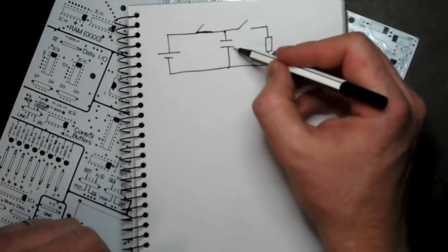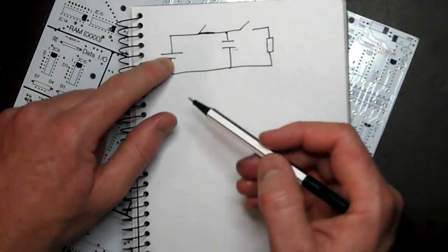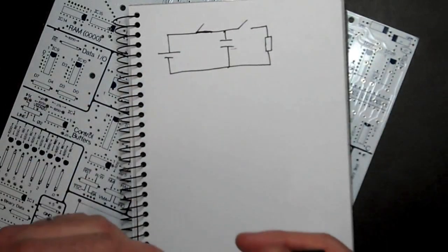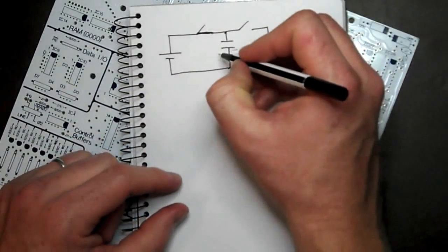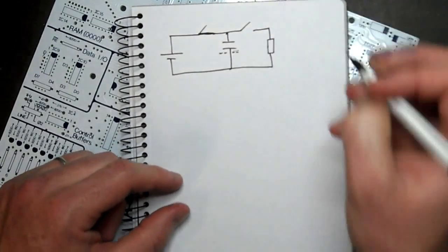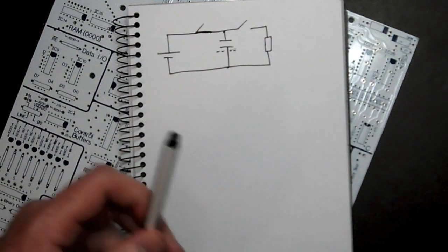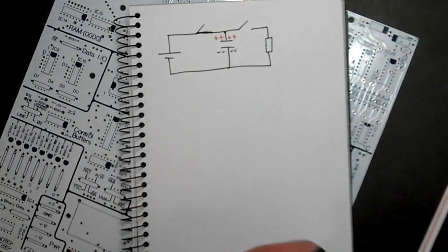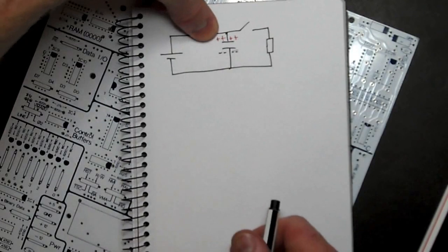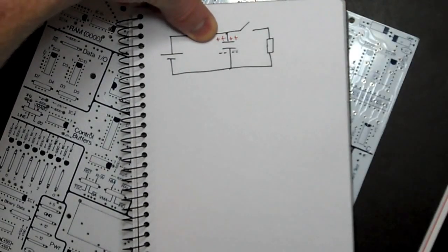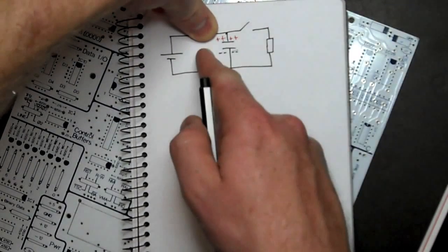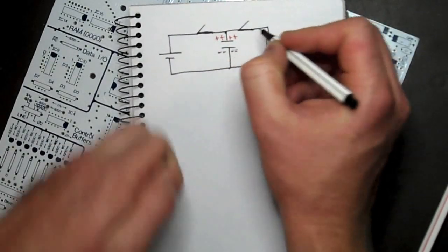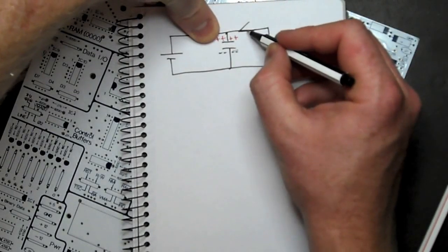So this capacitor will actually charge up to the full potential that we just applied. So the capacitor is now charged, and as before we'll have a net negative charge on the bottom and positive on top. If we then open circuit this, it will hold on to its charge. So leaving that open circuit now, I will now short circuit this one. So that's open, this is now short.